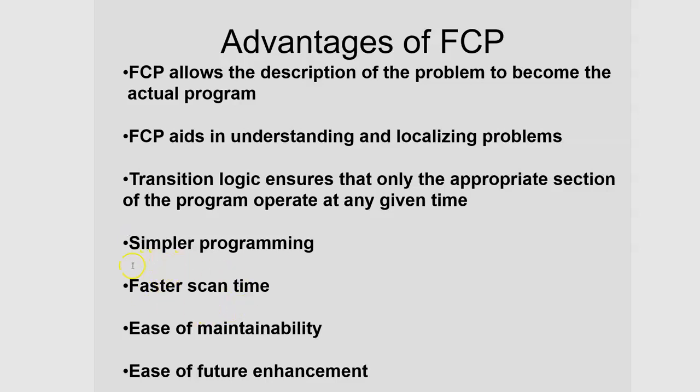Faster scan time for several reasons. One we talked about was you don't need as many or as complex interlocks. It's easier to maintain, so if things are modular, they're usually easier to, if I have to change something or update something, I can go right to one part of it and do that. And for the same reason, ease of future enhancement.